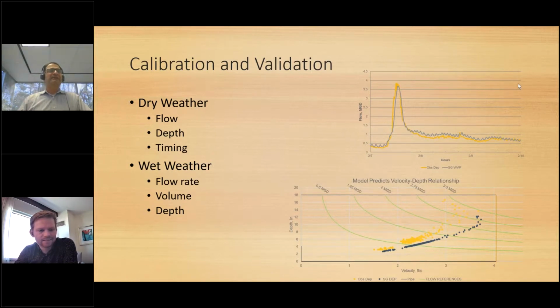But typically, and what I tell my team, is that either we need to fix it or we need to explain why it's not matching. There might be something in the field that is backing up that line that's not simulated in the model. It rarely works the first time. In some cases we have to put more effort in and change conditions in the model to match the field. But if it doesn't match, there has to be an explanation.